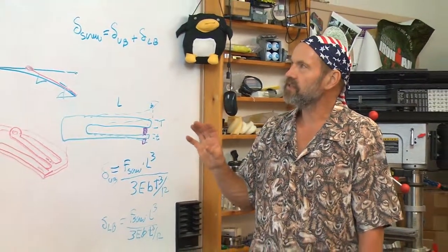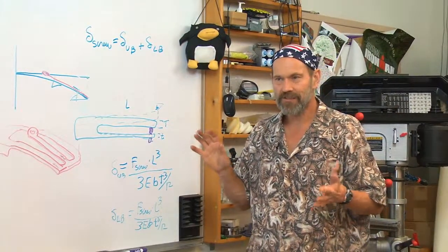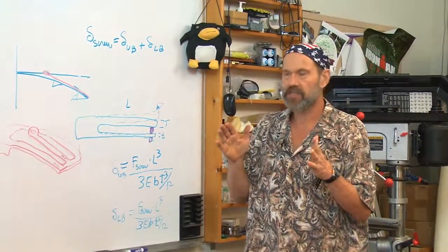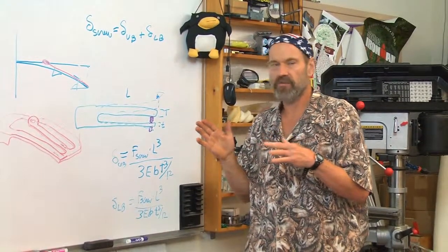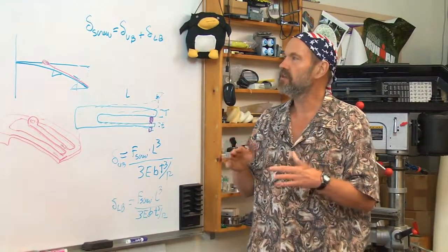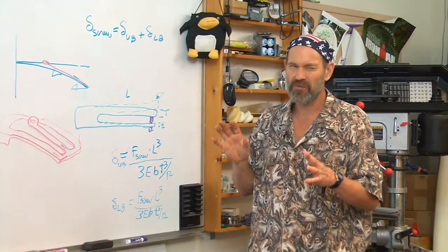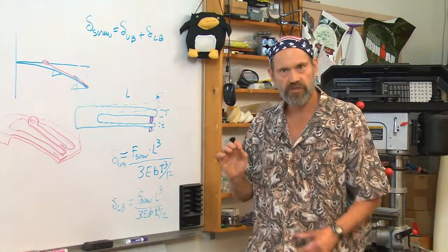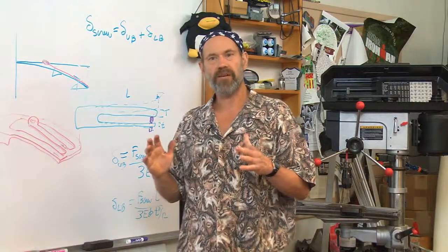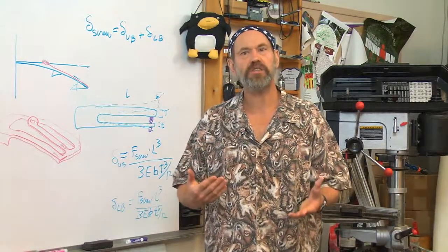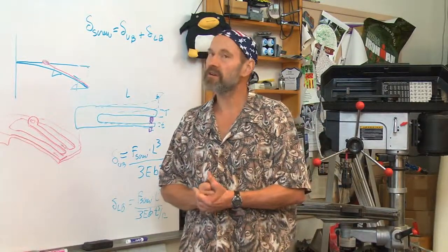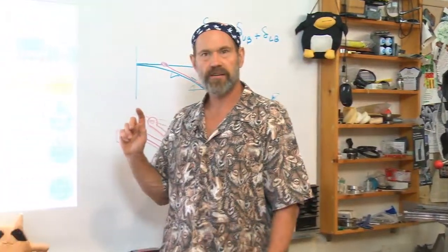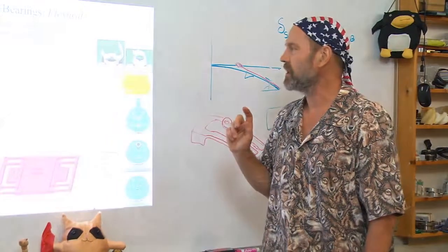So flexural bearings are so interesting because they can provide motion that has no backlash, no wear, and requires no lubrication. Their only limitation is that the range of motion is limited, but I can also use them not just as a simple bearing, but as part of a transmission system. Very, very powerful tool.